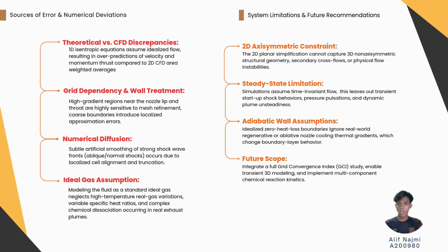To advance the research, future studies should include a grid convergence index to eliminate the mesh dependencies, utilize a 3D transient solver, and implement real chemical reaction kinetics.